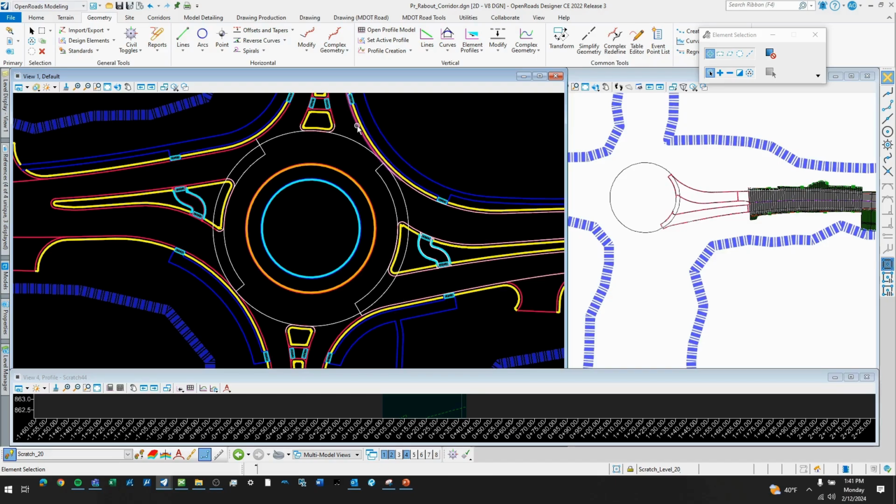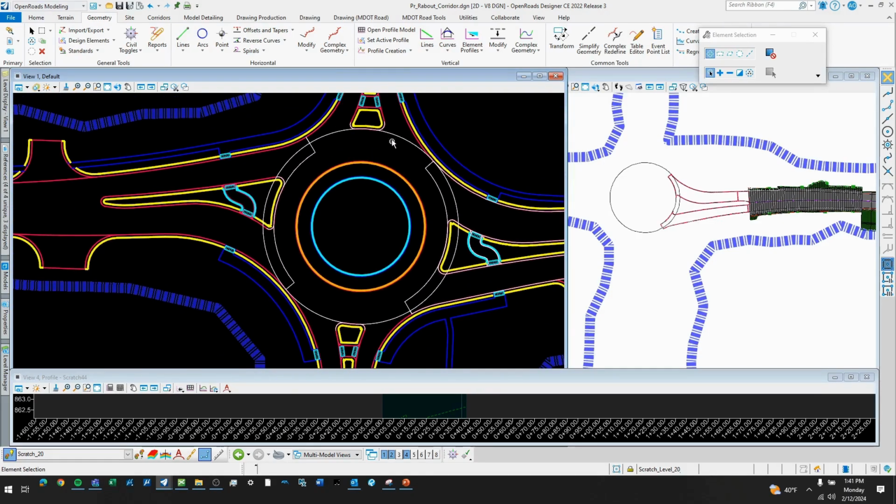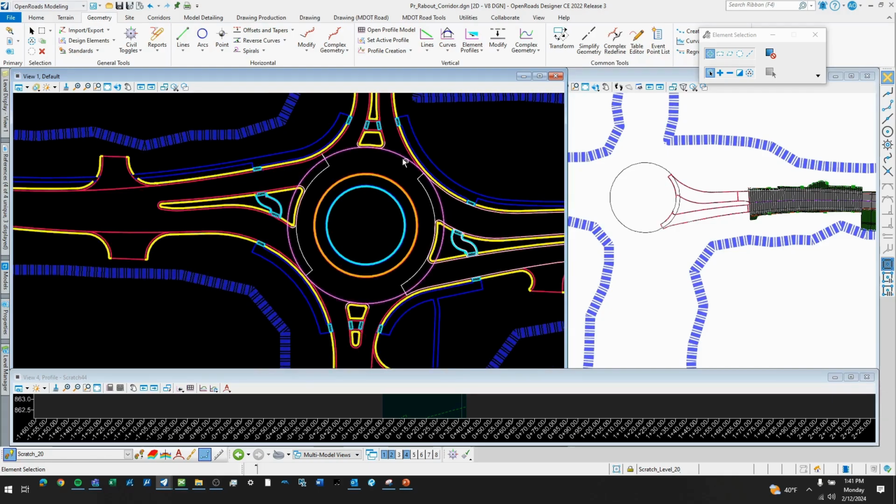A lot of it is going to go on these PGLs on the HMA level, which is red, so the white helps show a difference when I'm doing this. That first step then is really, you've got to run into a couple of different considerations. You're really just trying to map out what you want your elevation to be going along this ICD and what those PGL tie-ins are going to be.